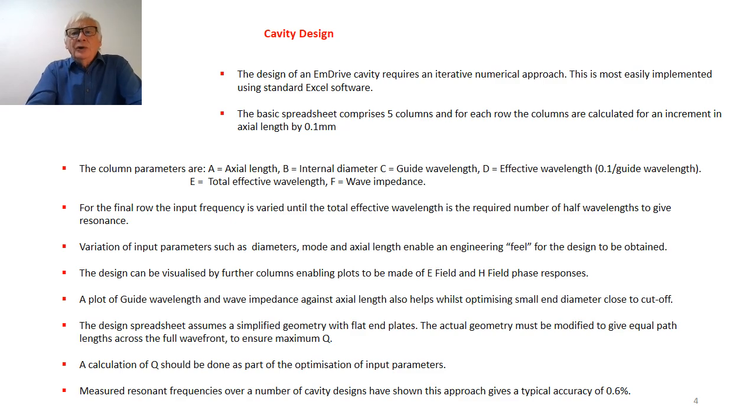And for each row, the columns are calculated for an increment of axial length of 0.1 millimeters. This has proven to be sufficient resolution to get accurate designs. Okay, the column parameters are axial length, internal diameter, guide wavelength, effective wavelength, which is 0.1 divided by the guide wavelength, total effective wavelength, and wave impedance.